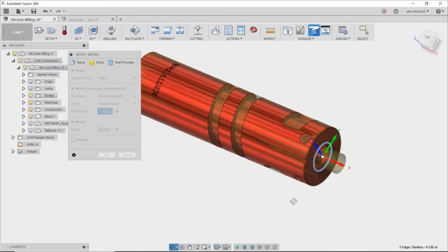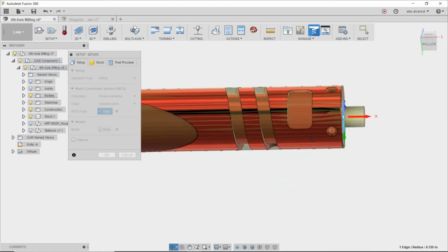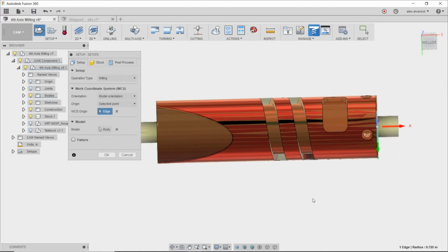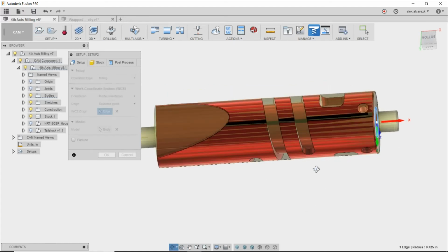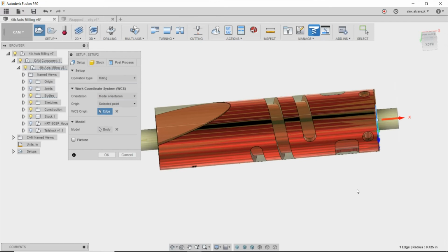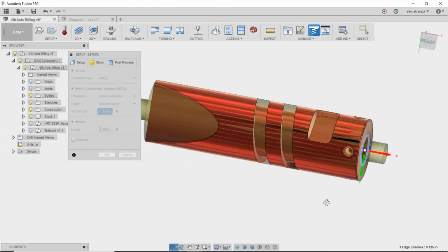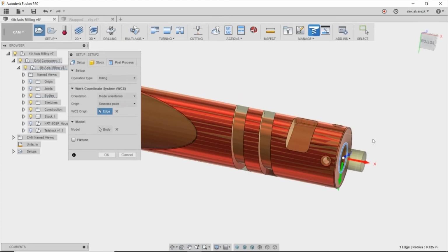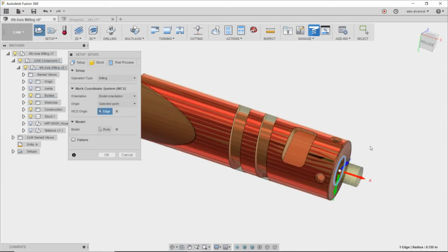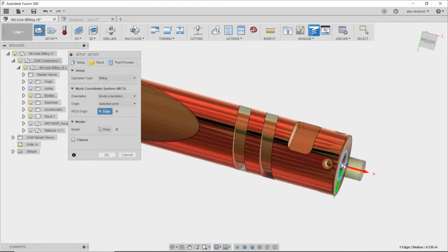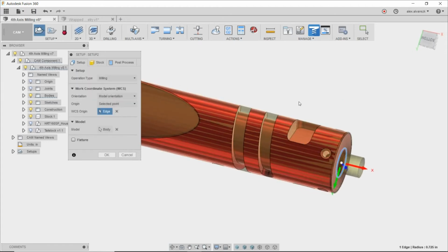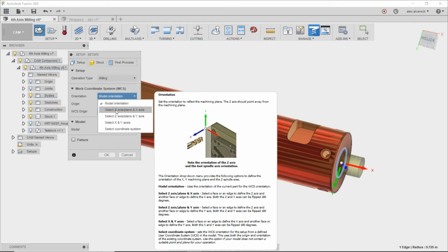Another thing you could do is take a look at some of the features that we have here. We have this flat pocket, this angled cutout, as well as this coil going around the part, and then this wrapped pocket on the other side. So instead of having the machine rotate, let's just have this be the top of our z-axis. In other words, make the z-axis perpendicular to the top face, so we don't get any rotation when the first operation happens. So what we can do is set this as select z-axis.